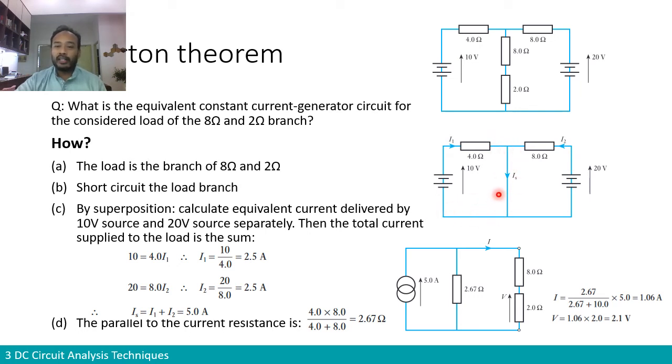That's why it's called short circuit: instead of going through the resistor, current prefers to go through the path with less resistance. Here in this case there is no resistance at all, so it will go through IS. So I1 is just the current in this loop. It is therefore equal to 10 volts divided by 4 ohm, which gives us 2.5 amps.